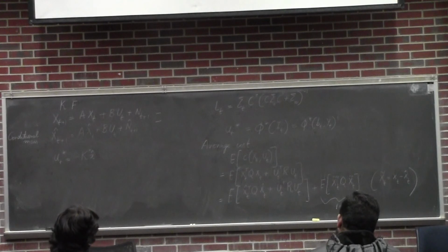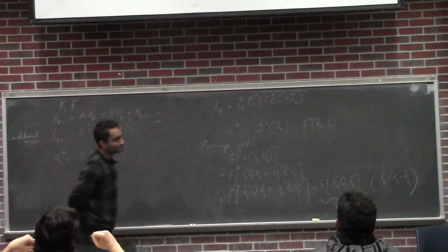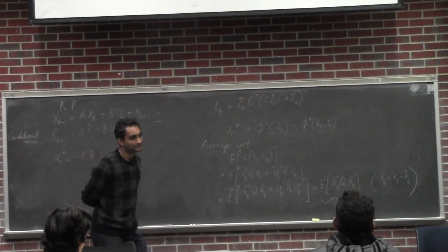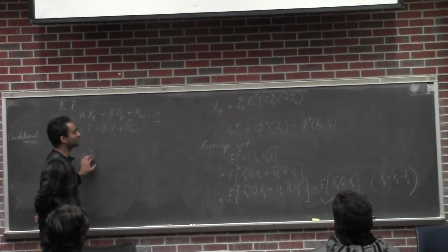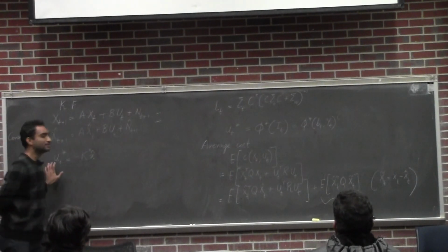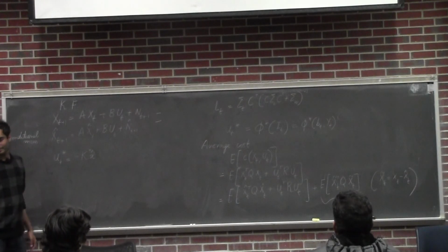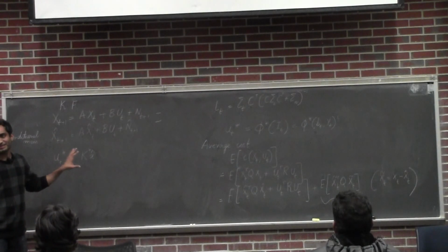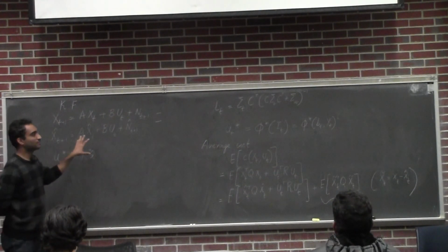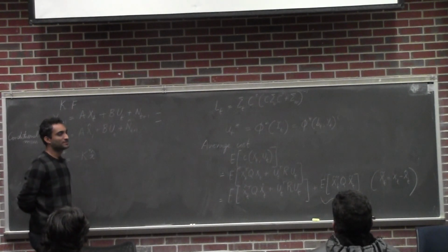So in this case, you just feed your state information or your estimate into your typical policy for these systems. You don't have to develop some new controller. You're just saying, here's my estimate. Yes, because the Kalman filter gives you the best estimate of the state, and then you use that in your state feedback, and that's the best policy that you can get. And this is true only in the case of LQG. This is why the Gaussian assumption is also essential, because if you don't have the Gaussian assumption, the Kalman filter is not the optimal filter.